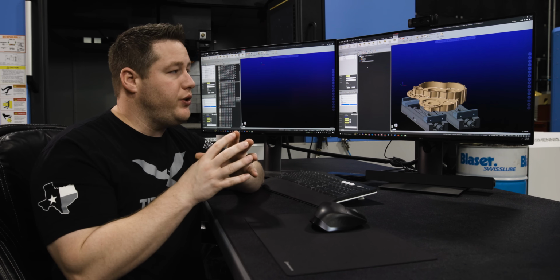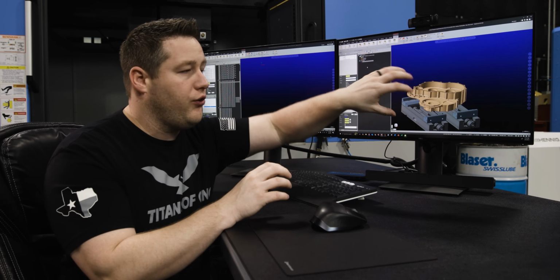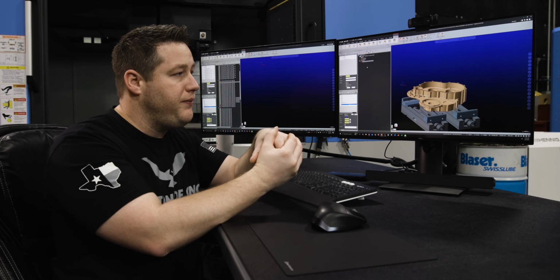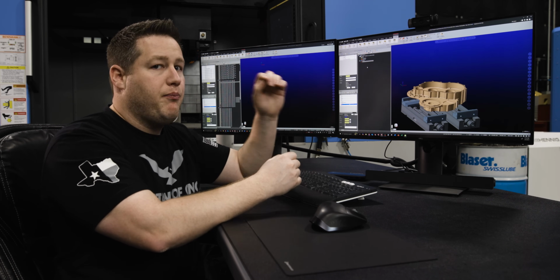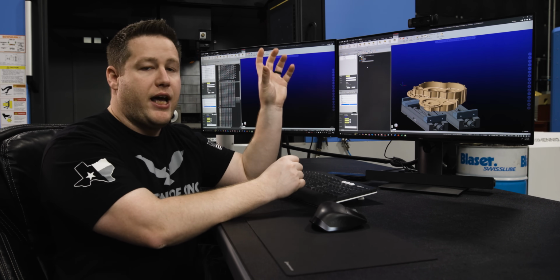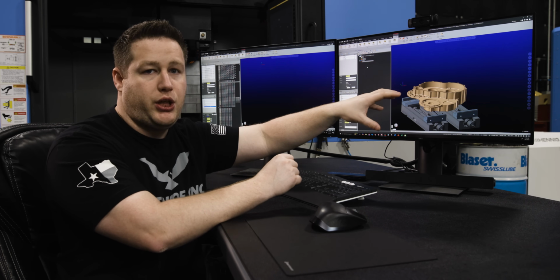So that is one thing that you need to know, that if this was a part that we need to get to all 6 sides, and we're doing it in 6 operations on a 3-axis machine, then you will need to create 6 different machine groups, but the stock will all be that same stock that you use in the first machine group.